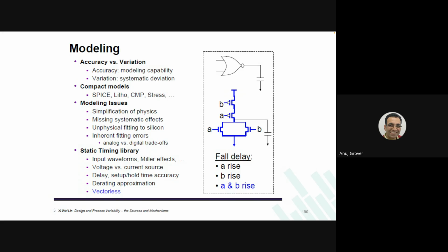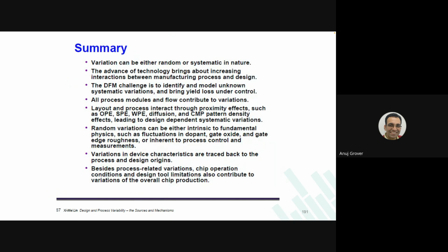Even in verifications, we will talk about them in the next class. Even in verifications, what we saw was that these OCVs, the margins you leave for on-chip variations in your timing analysis, were becoming exorbitant. Memory performance is not improving. Memories are in the critical path everywhere. And the customer is expecting that you will be able to operate the system at double the frequency or at 20% higher frequency. How will you get it?